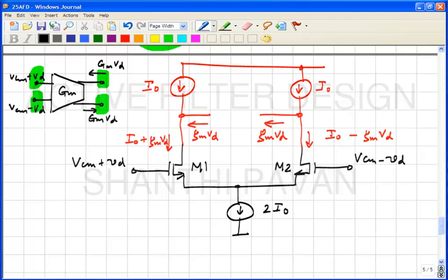Assume that the output impedance of the transistors is infinite when they are operating in saturation. That's true. What else? What are the assumptions we are making? Current source is infinite output impedance. Sure, that's fine. That should be matched, yes. But is there a fundamental thing that we are missing? That's already what he said. I mean, VGS being incrementally very small is equivalent to saying small signal operation. The key assumption is that M1 and M2 have to be in saturation.